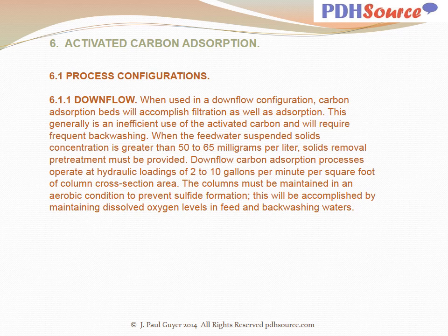Downflow carbon adsorption processes operate at hydraulic loadings of 2 to 10 gallons per minute per square foot of column cross-section area. The columns must be maintained in an aerobic condition to prevent sulfide formation. This will be accomplished by maintaining dissolved oxygen levels in feed and backwashing waters.